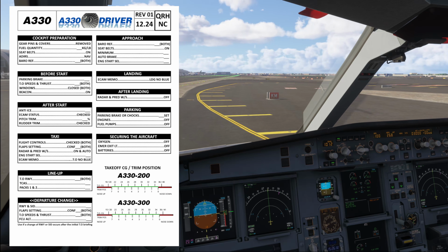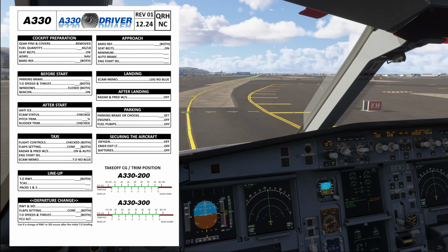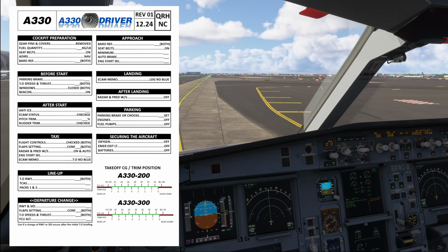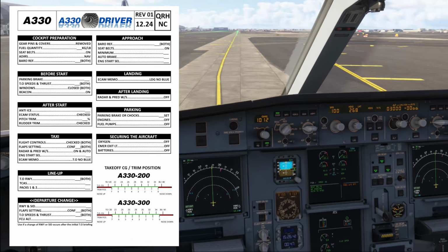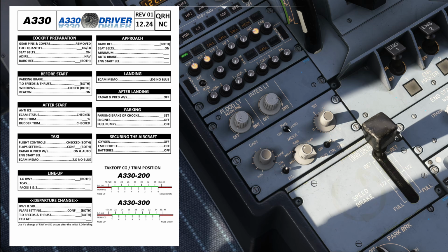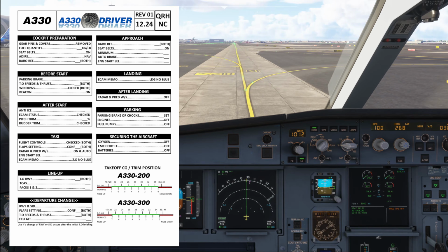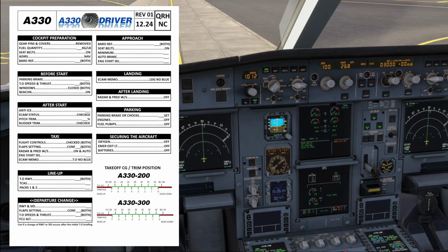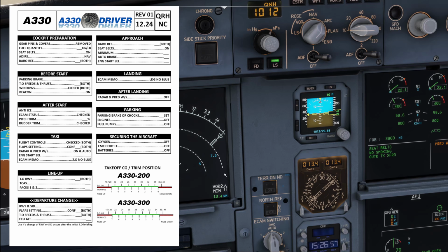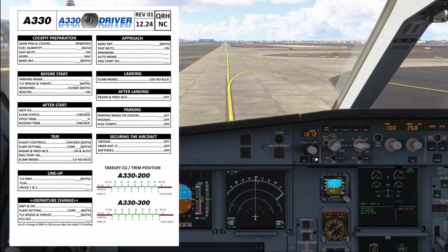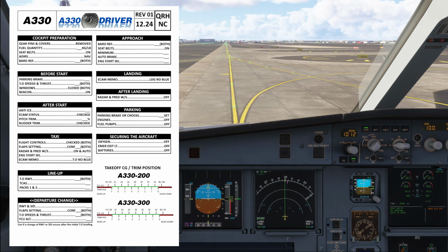checklist. The checklist itself is fairly easy: radar and predictive wind shear, and the pilot flying checks on the pedestal that the weather radar and predictive wind shear switches are off. Now you will find those located right down here. So you've got weather radar system off, predictive wind shear off, and that's the after landing checklist completed. Note that you can verify those on your flight instruments by first of all seeing that there is no indications of the weather radar down here, and seeing that you have the predictive wind shear off annunciation in your ECAM. And that's the after landing checklist complete.